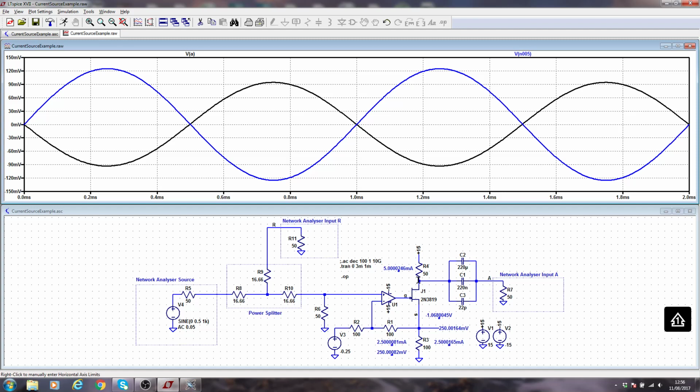They often, or not often, but many of them, some of them at least, do, because if they're in current mode, they have much wider bandwidth, usually, depending on how it's been designed. So there are lots of circuits where you want a current input to test it. If you want to test your transimpedance amplifier and your photodiode system, you might want to use some circuit like this. So I don't really want to use R4. I don't really care about the DC part, and I'm not interested in the 50 ohm output impedance.